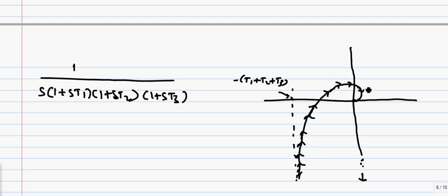Okay, and the arrow marks will be in this direction, as omega equals 0 here, and at this point omega is tending to infinity. And we would be interested in the frequencies at which this plot is crossing minus 180 degrees, and the frequency at which it is crossing minus 270 degrees. Let's write these equations.